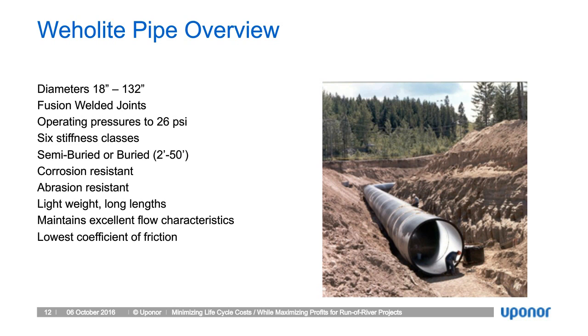We have multiple stiffness classes in case it's to be buried or semi-buried. If it's buried, anywhere from 2 to 50 feet. The material, just the characteristics of HDPE: it's corrosion resistant, it's abrasion resistant, it can handle high or low pHs if that was an issue, the salinity of water, or salinity in the soil. So it's a very robust material.